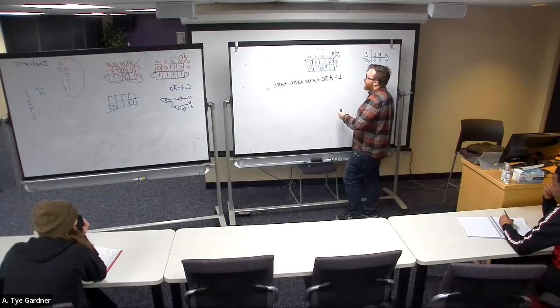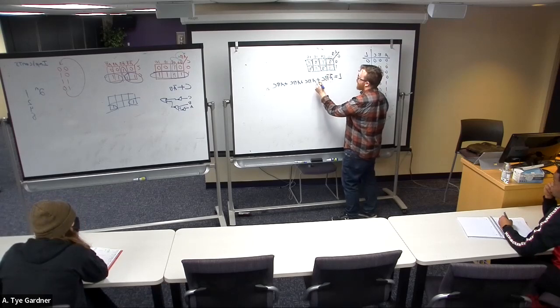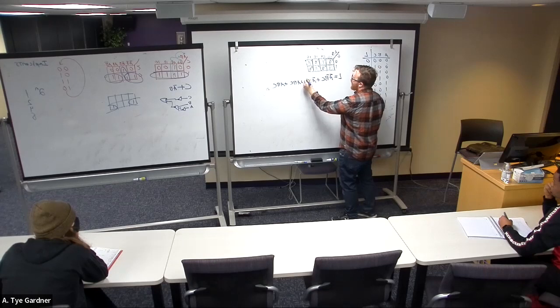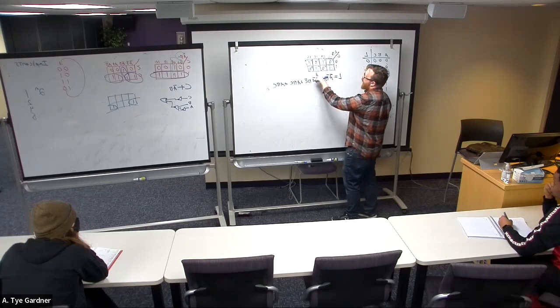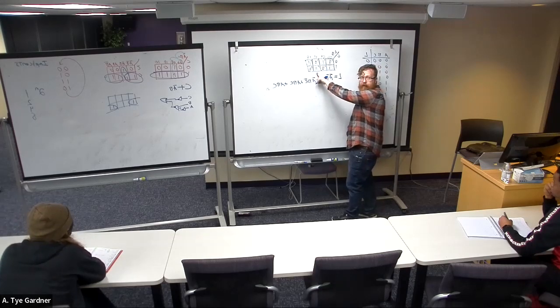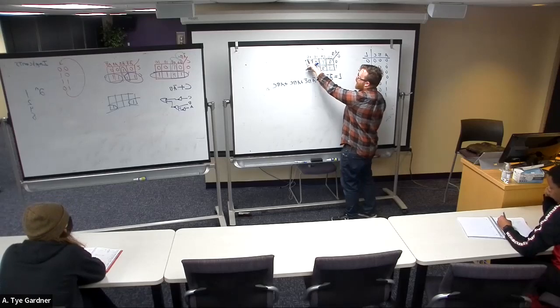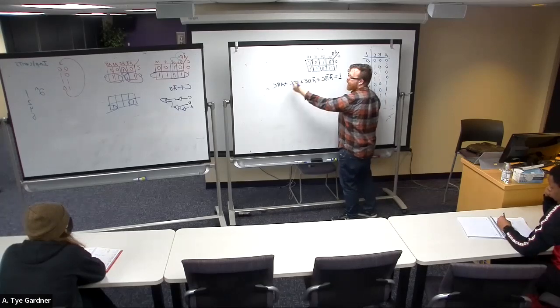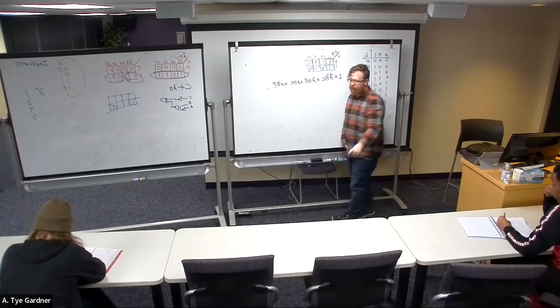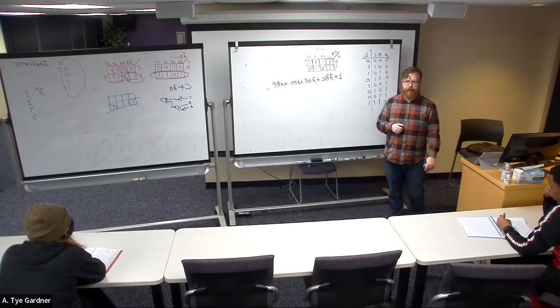And then it's just a matter of going, well, it's not A, not B, not A, B, not C. That one is A, B, C, right? Because 1, 1, 1. And this one, A, not B, not C. I don't have to do any Boolean algebra because my K-map told me this is as simple as it goes.